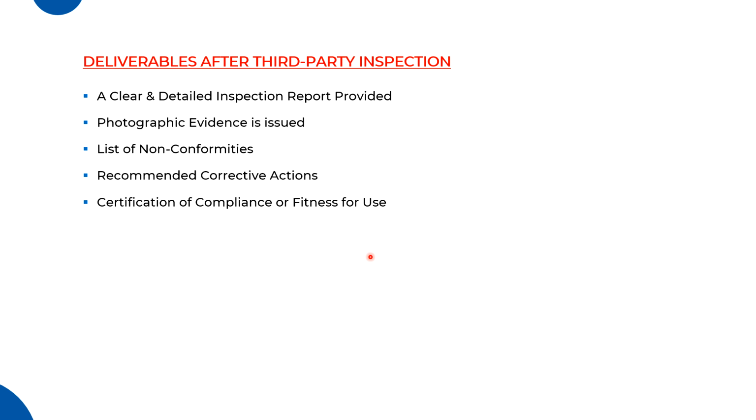Every equipment on the rig should have a certificate of compliance or certificate of fitness. The rig contractor has to ensure that they have the OEM inspection certificate and that all the documents provided by the OEM for every equipment are ready at the rig site, in either soft copy or hard copy. This is very important, because it can be asked for anytime by the client.